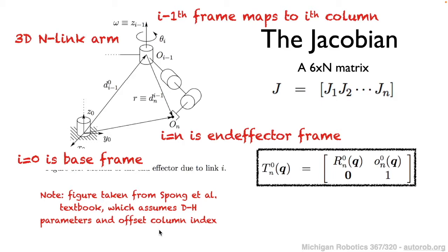What you'll recall from forward kinematics is that we will be able to produce a transformation from the end effector frame to the base frame, to the world frame, which will be based on the current configuration of the robot. And that transformation will be represented as a homogeneous matrix. So this is what we looked at, you'll recall, in assignment 3.